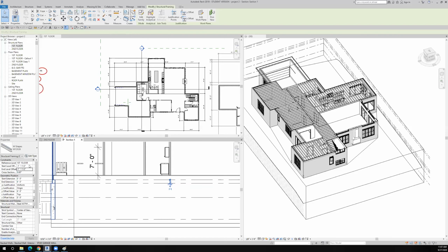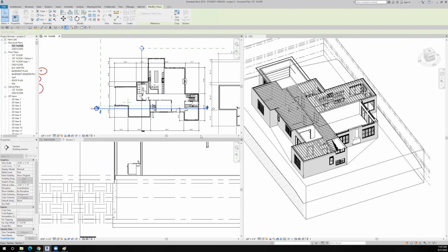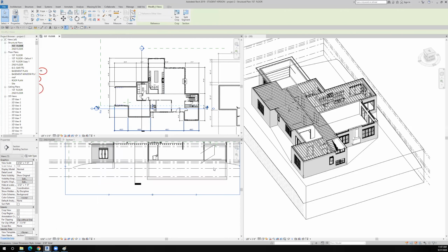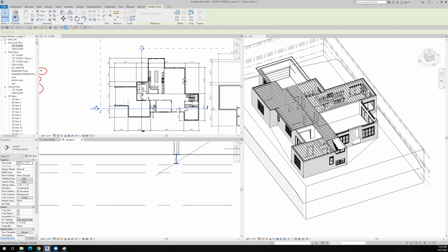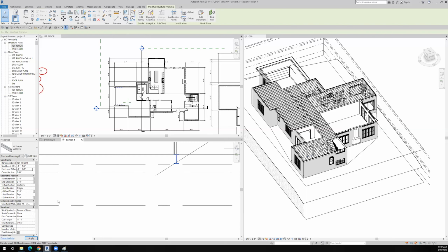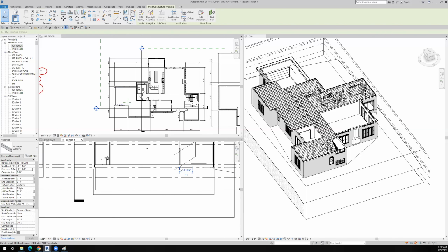So I'm going to copy this, Control C, and I need to go and look at where other places I put that steel beam, because it's probably in the wrong spot too. So I know I have a steel beam underneath here. Let's take a look at that now. Sure enough, it went in at the first floor. So I have to change it. So I'll come over here, Control V and Control V. That just saves me a little bit of time of typing, and apply it. So now the steel beam is in the right spot.